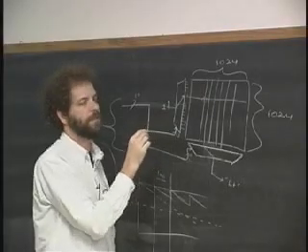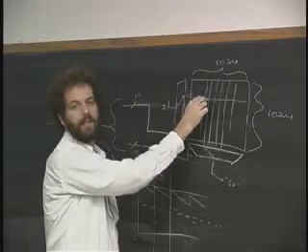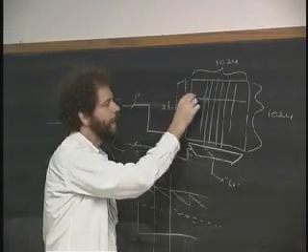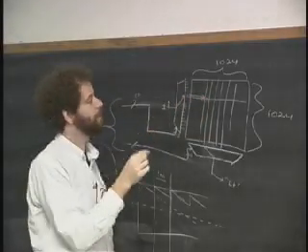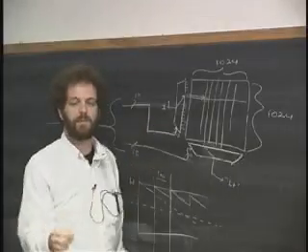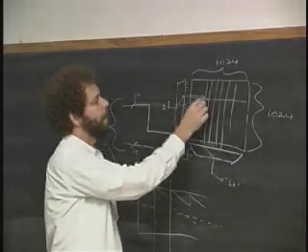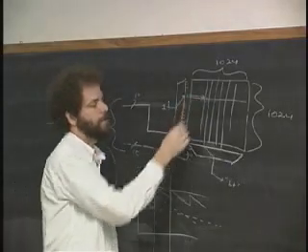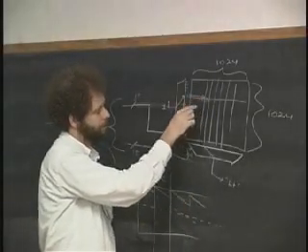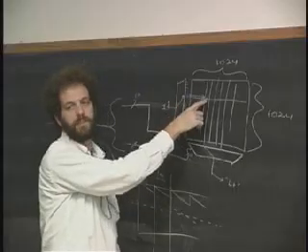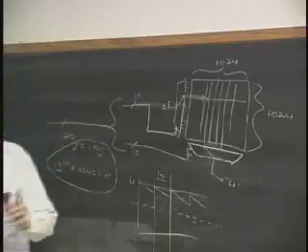And the designers of these chips take great pains to figure out, if I put a high voltage here, what does it look like here? And it turns out that it changes how fast it takes for the high voltage to get to this place. And we're going to talk about that. What limits the speed of the memory is just what you're saying, the time it takes for the water to get down the river from one place to the other: the resistance of the wires, the capacitance, which is kind of the size of the river on the way to the final place, to the bathtub here at the end, will limit how long it takes to fill this thing up. And that's the fundamental limit to speed on the thing. We are going to talk about all of that stuff too.